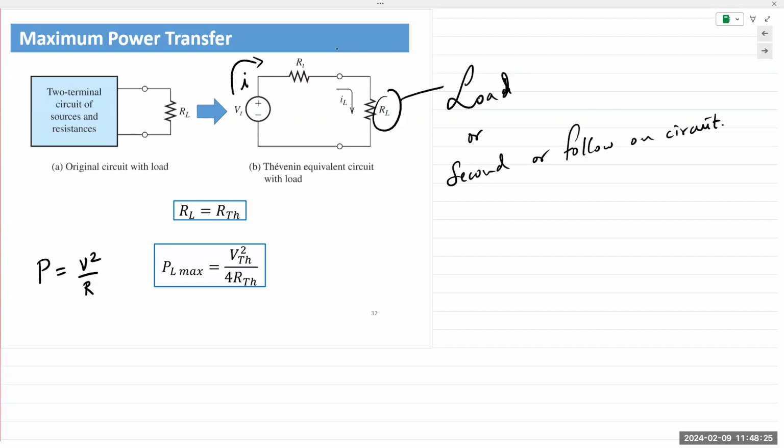In cold weather, the electrochemical reactions inside the battery take place at a slower rate. So the battery voltage remains the same, but because the Thevenin resistance of the battery is now very high, a lot of that battery voltage is dropped inside the battery itself, and there's not enough voltage to supply to the ignition coil. And so Thevenin resistance increases at cold temperatures, and so our car has trouble starting in the morning in very cold environments. So just real life examples.